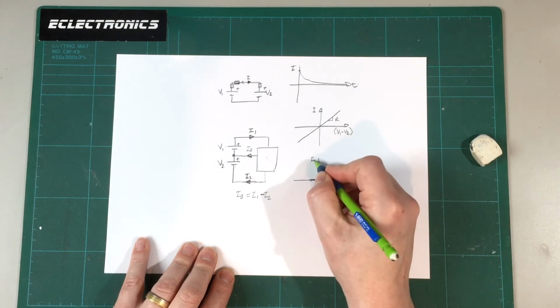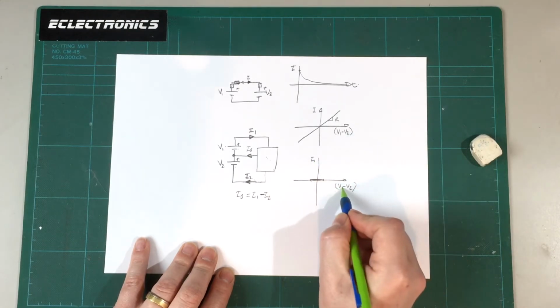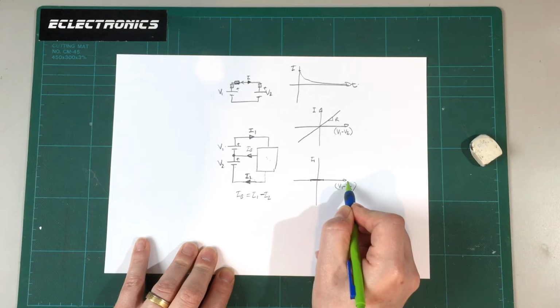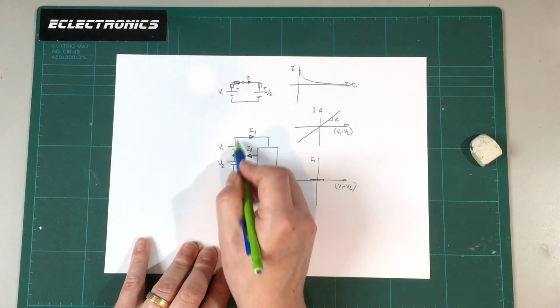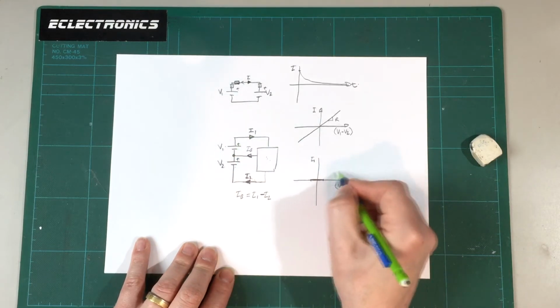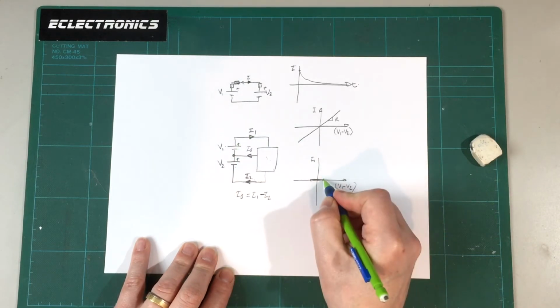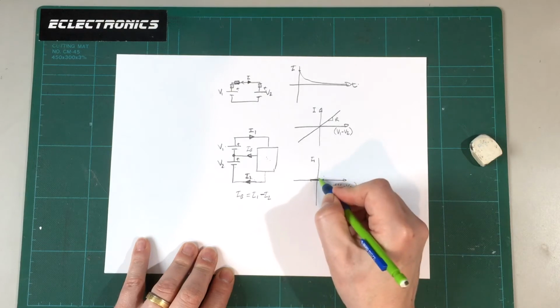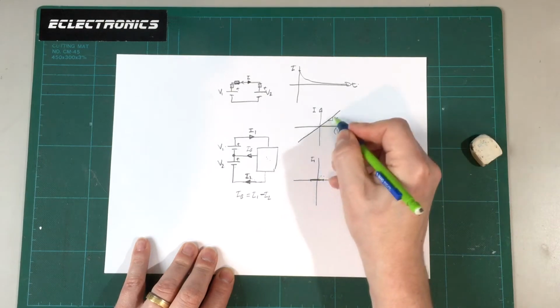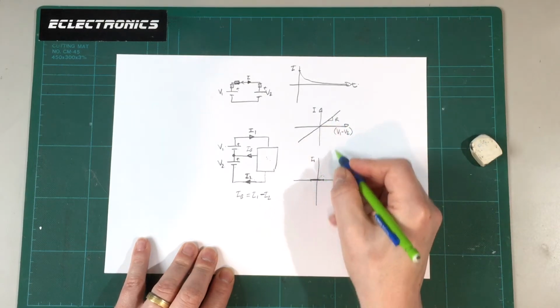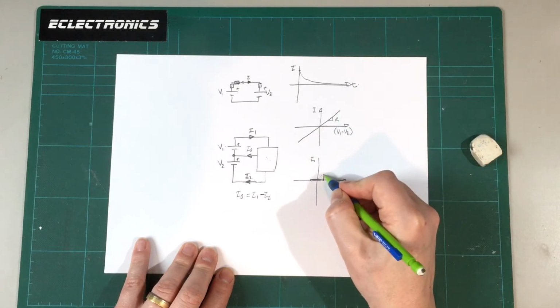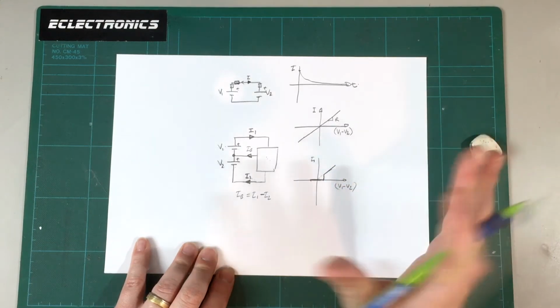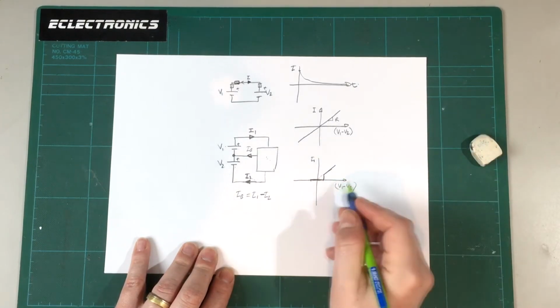Now, in terms of I1, we've already said if V1 is greater than V2, that puts us on this end of the line. We'd expect I1 to be positive in that case, because charge will be drawn out of cell 1. So we're going to be in this quadrant. So it's going to either suddenly jump up to some value, so let's say it was starting at 0, a bit like a resistive balancer here. The current might jump up to some value, then it would probably ramp up in some way, some characteristic that's sort of proportional to the voltage difference is what you'd expect.